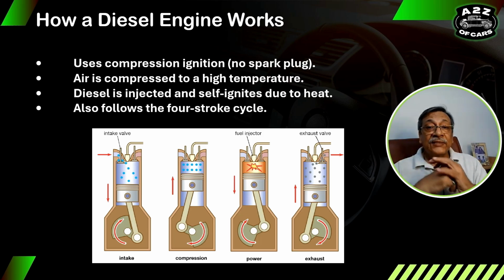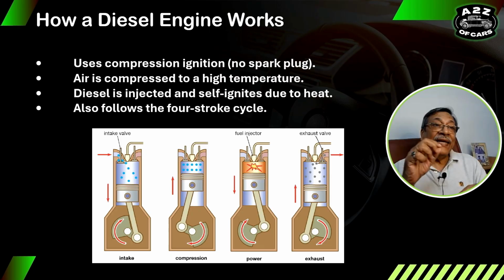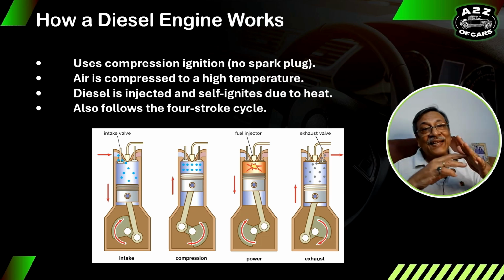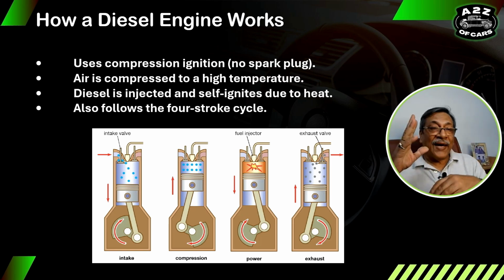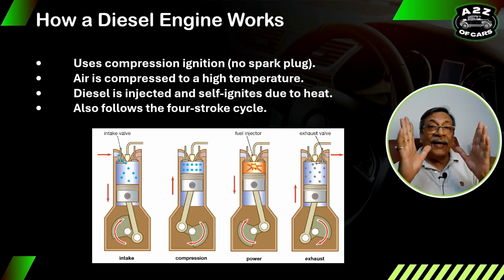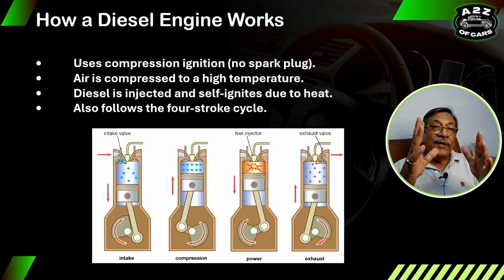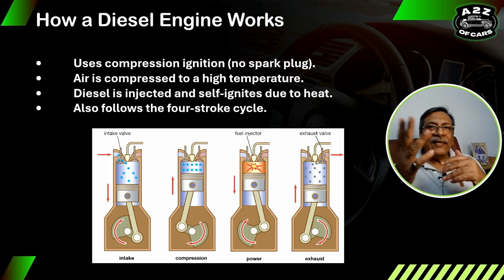So how does the diesel engine work? We have seen the petrol engine. Now let's see how the diesel engine works. Same four strokes, but the difference here is, in the diesel intake stroke, only air comes inside from the intake valve. What I said in the petrol engine, that for petrol you need spark, but in diesel you need high temperature. That's all. If you inject diesel in a high temperature, it will catch fire automatically,